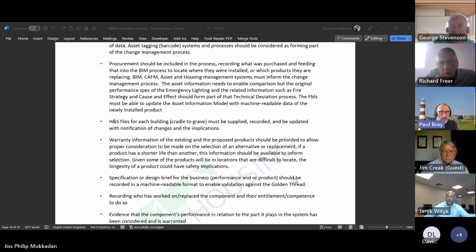And then perhaps it comes from lots of offices being made into an open plan. So the layout of the emergency lighting scheme wouldn't really reflect the way that people would evacuate from the building. I think this is really important because this is what happens in a lot of buildings, that the building changes, not just for emergency lighting, but for everything. And that's what happened at Grenfell Tower. You make changes to the original layout or structure of the building, and it has that consequence to the way the building would operate in a fire situation or any other emergency. Okay, anybody else got anything to add in?